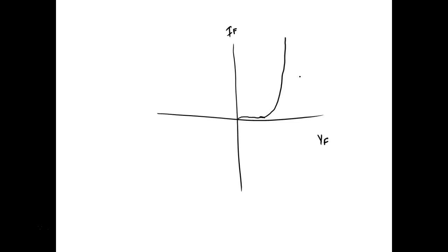Make sense? Of course, we're not going to see this because we're going to start out right around here, which is going to be the 450 millivolts. We're going to see very little current flow through it because it still hasn't fully turned on, right? Understand? And then we're going to keep going up till we get about 0.75 volts, which should be up here somewhere. And then we're going to have other dots that we come up here and do. So once you get all these measurements, you should be able to draw that curve. That makes sense?